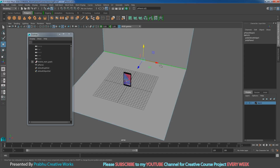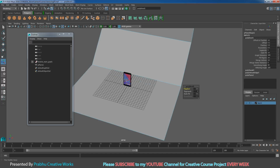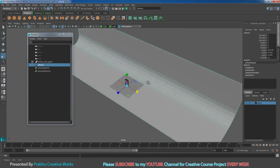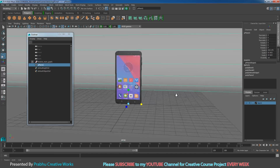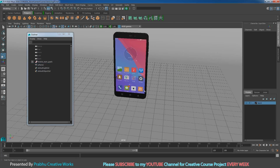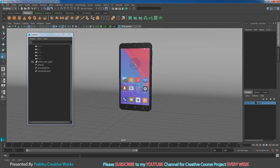I will select my edge over here, shift right click and choose bevel edge. I want to decrease my fraction amount and increase segments to 6 or 5. Right click and choose object mode. I will select this object, press R and scale in X very big. That means when you go closer, I will deselect outside. So it will look like an infinity background look over the backside.